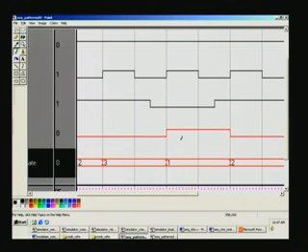So, if you look into the source Verilog code, you will see that. We would have put always at positive edge clock. So, only at the positive edge of the clock all this happens. So, this was earlier in the second state, at that point of time only at this stage it is going from 2 to 3, and right at that point whatever is the actual input here, only that is being taken and then processed accordingly.